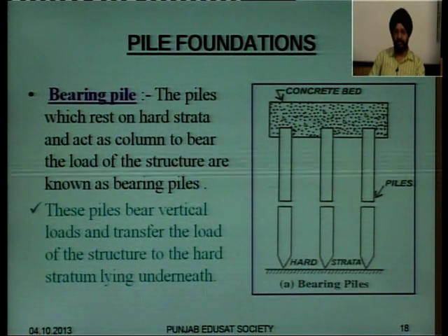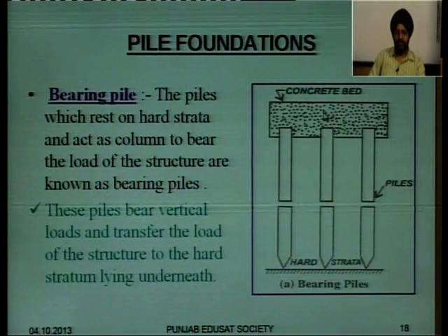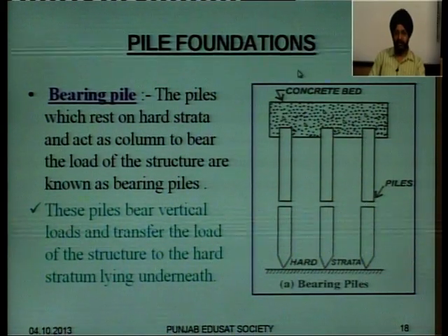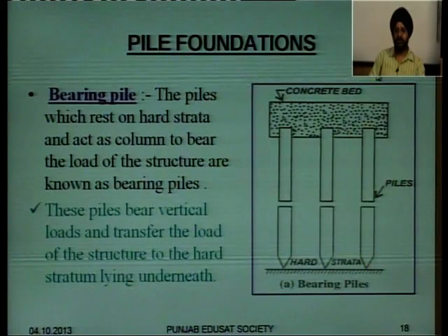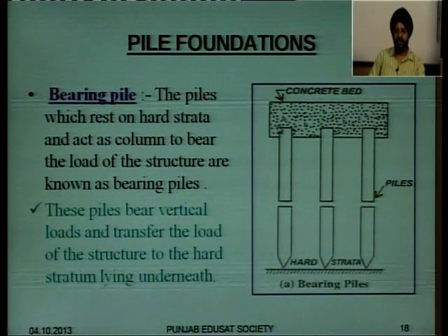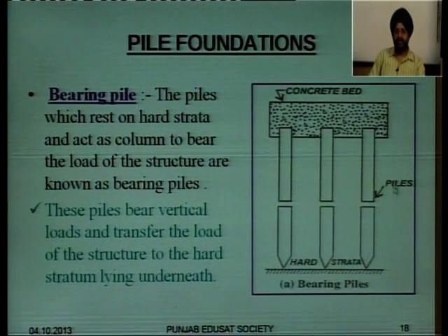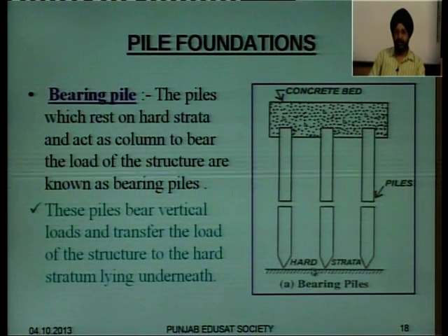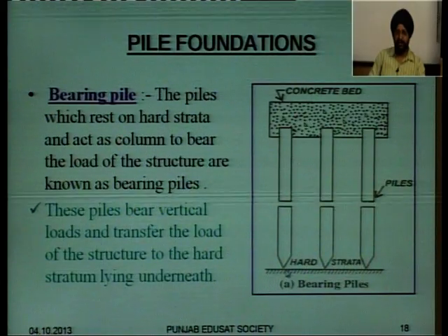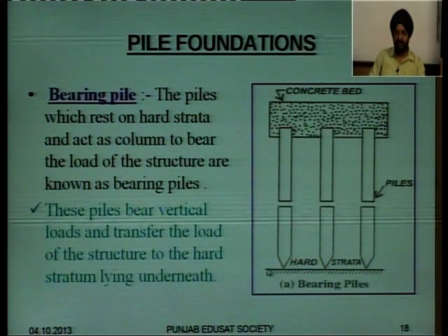This is a concrete bed, and if you concentrate on this diagram, above this concrete bed we are going to erect the piers or abutments, and these piles are inserted in the soil and deepened till the hard strata.